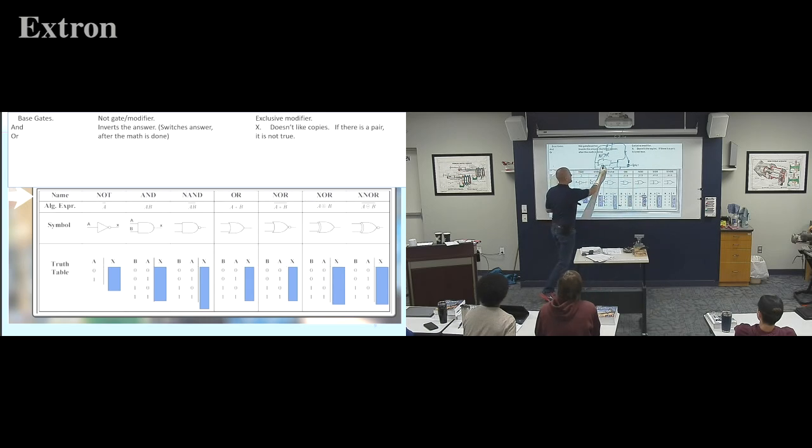Now, if I close this switch, my electricity could run through that switch, it'd run through the solenoid, that would make my solenoid suck that up and open. Now I don't have power to the light bulb anymore, so if either one of those closed, there we go, we'd get the 0. If we close both of them, I still have my solenoid, sucks it up, no light bulb. So there we go. We drew our NOR gate.